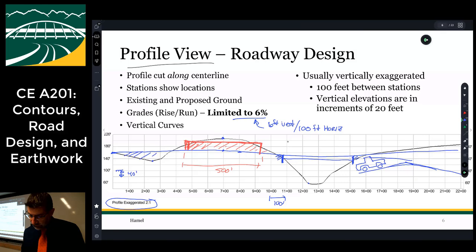Here's some fill. Over here is probably some more cut, right? It actually should be a little lower than that. And so I'm going to have some more cut over here. And again, I can do a similar thing over here. I can probably come up with some sort of square cross section that looks like that and guesstimate, right?